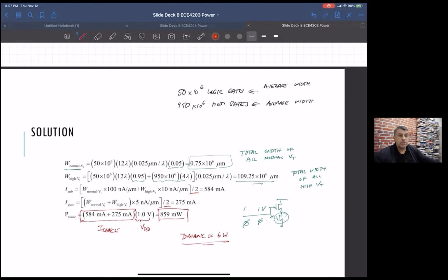The reason they're still there is that their leakage currents are really low. They don't run very fast, but your pacemaker isn't going at a gigahertz. It's going much lower, but the leakage currents are a lot less. So if you look at what's available in the industry, especially for biomedical circuits, you'll see a lot of these older processes, and a big part of it is the leakage current.